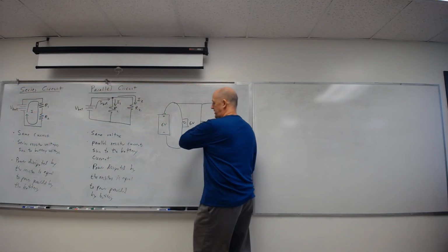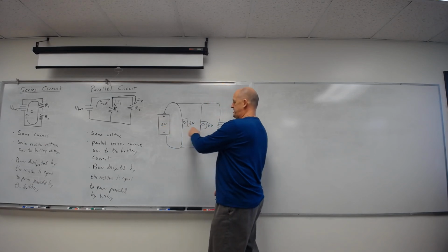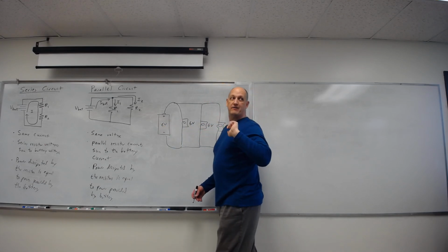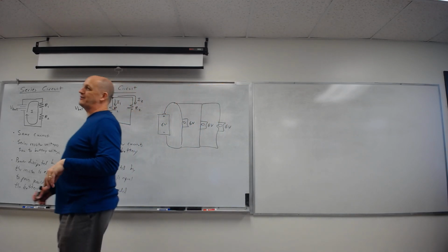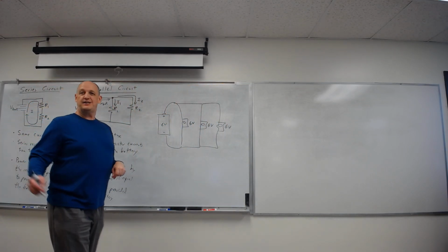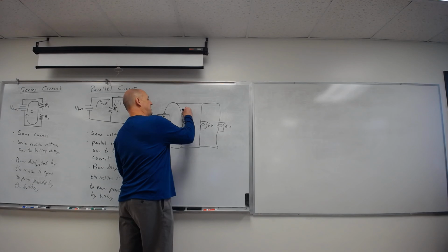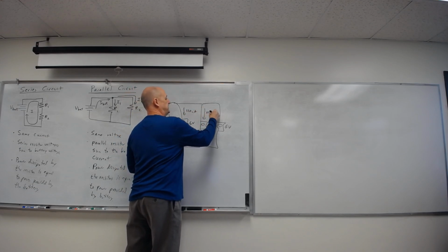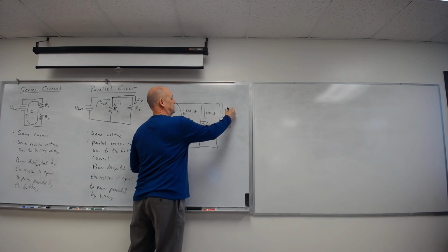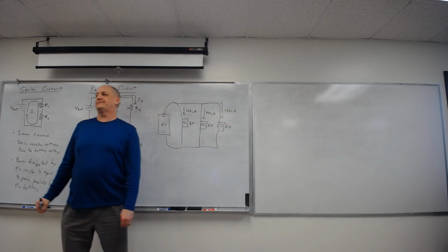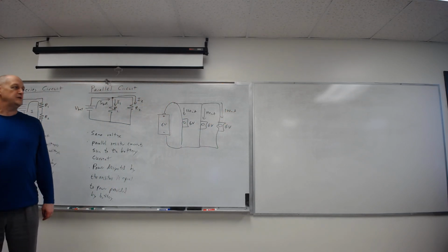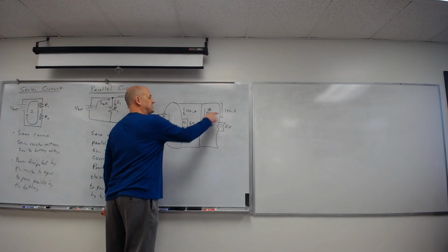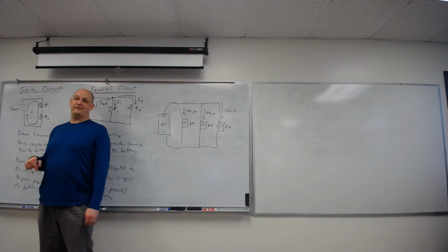Now, when you built this circuit last week, you had 6 volts total. Each of these should have been 6 volts. Like I said, nominally, they probably pulled down the battery to about 5.5 because the battery can't actually provide the current. And if you measured the currents, these currents individually were about 120 milliamps each. You might have gotten 100 if the batteries pulled down enough. If you got vastly different ones, you measured it wrong, and I noted it.